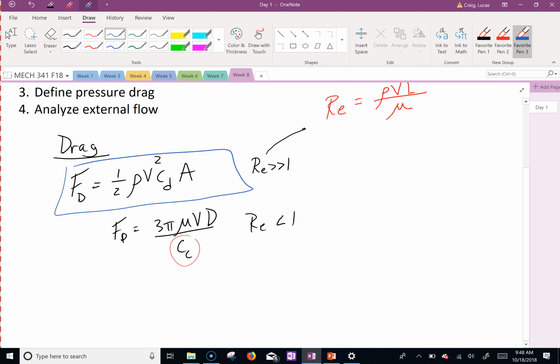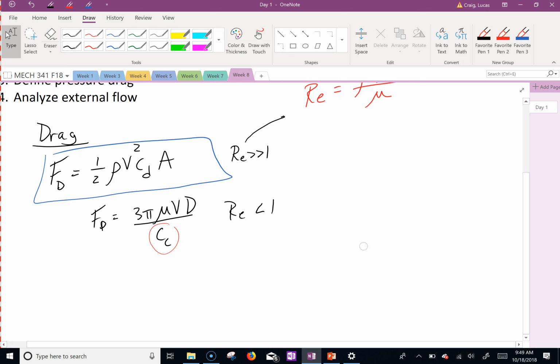I wanted to let you know that there are actually two different types of drag. This one you actually used. You remember the falling ball viscometer? That's the equation you used there, because with that you can find the viscosity of the fluid. When you did dynamics, or even physics, here's a ball, and it gets launched off at some initial velocity, shoots in the air. Do we ever use drag? No, you neglect it. Why? Because it's pretty hard to actually find the velocity squared, because it's nonlinear.